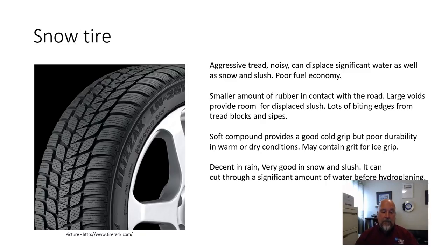So a couple things to note as well. In that compound, you do find some manufacturers putting some special processes into the tread compound itself. They'll put grit like sand or cork into the tread, just so that if you get down to an icy surface, there's something gritty to grab the ice. Some manufacturers also make the tread rubber kind of foamy, so that when it cures, there are all kinds of little air pockets, and when the tire wears, those air pockets form little suction cups to try and grab the ground. So there's a lot of tech that's gone in to try and make the snow tires work well in the winter.